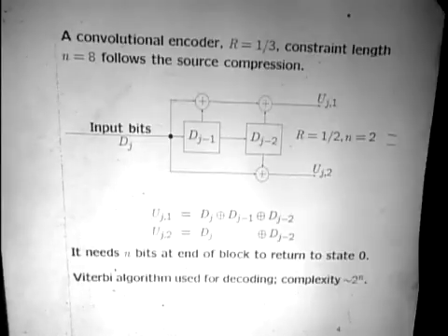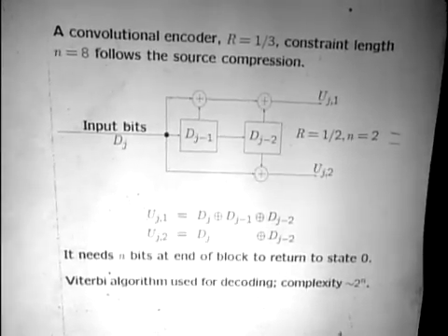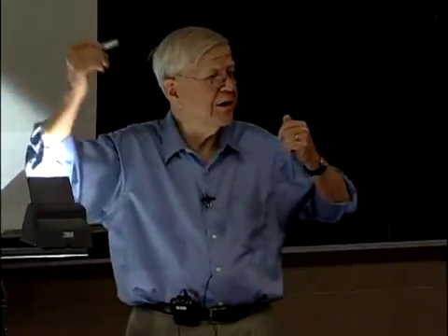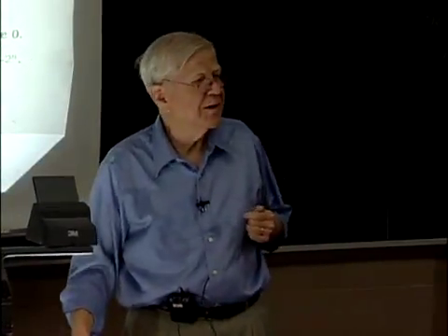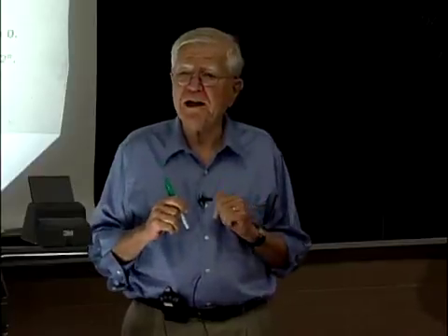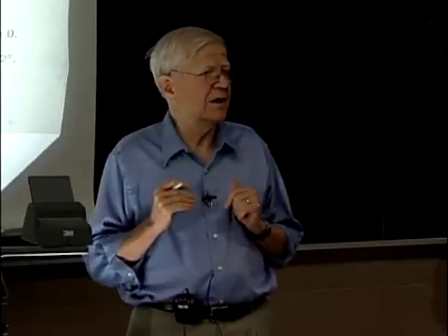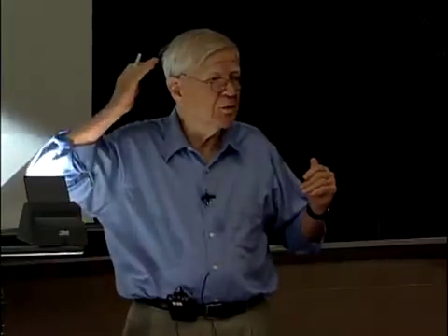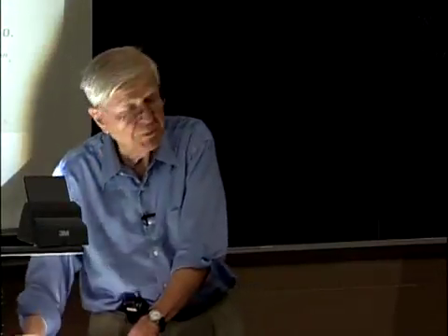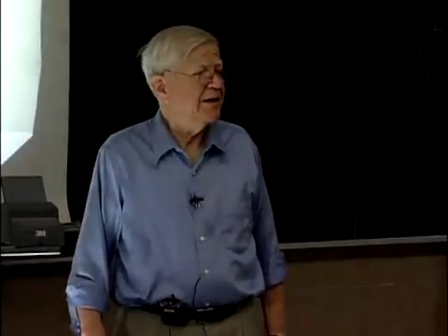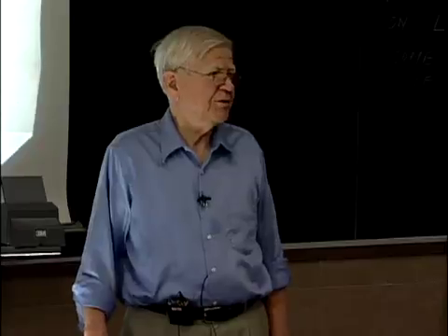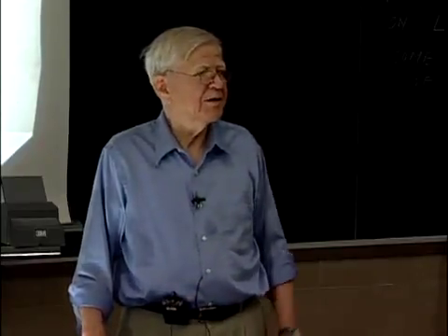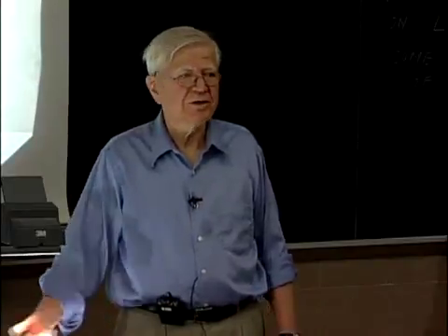If you think in terms of finite state devices, think of it this way. You have a device here which has 4 states. Somehow, the decoder has to realize at each instant of time, if it's going to decode, it can either decode the bits here, or a nicer way to think of it is it decodes the state at each instant of time. If it decodes the state at each instant of time, it doesn't really have to have any memory. As soon as it knows what the state is at 1 unit of time, then it has a very simple decision to make to figure out what the incoming bit is and what the state is at the next instant of time. And what a Viterbi decoder is, is something that does maximum likelihood decisions on the state.